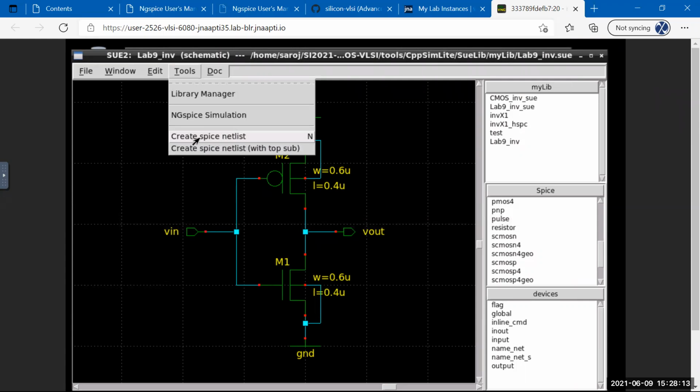Now, if you had all your voltage sources and everything inside the schematic, you would just use this, netlist it out, and then go there and add whatever commands. But the problem is, for example, writing a .measure and all that, you have to create instances for it and write those commands. So it's best you restrict this to only your circuit, and all your test bench stuff, like writing voltage sources and measure statements, you do in SPICE like you were doing before.